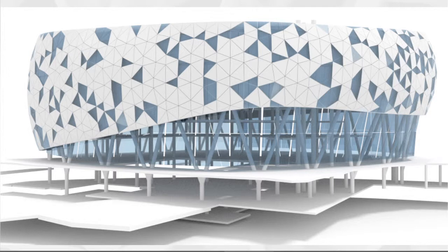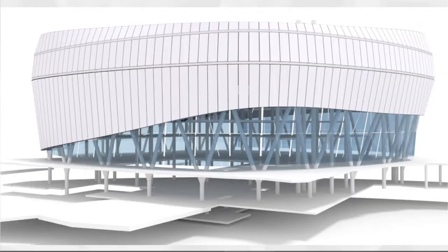There's some initial renderings where we tried to actually regularize the panelization as it gets mapped to this skin. But I'm sure many of you have tried to do this. There's a problem, and the problem is that it's impossible to exactly map a pattern that's been defined in the plane to a curved surface. And this has implications because patterns that are in the plane often exhibit really nice properties, like repetition of panels. You know, it's one thing to have 7,000 panels that are one of 3 types. And then when you map it to the surface that you're actually going to build, suddenly everything's unique. Everything has to be custom placed and custom manufactured.